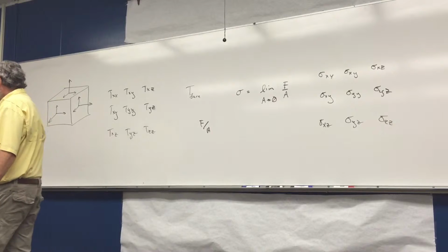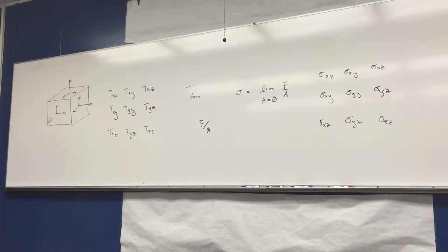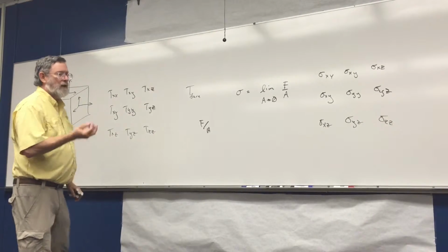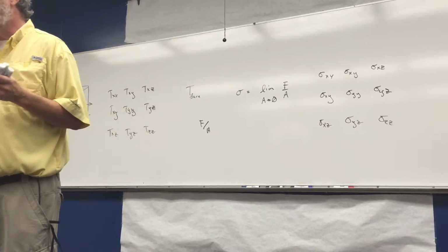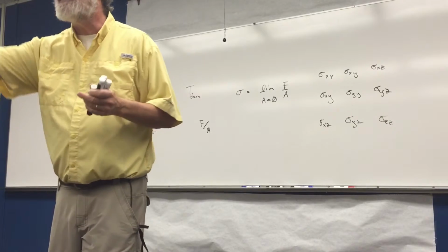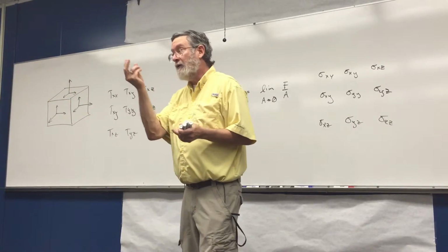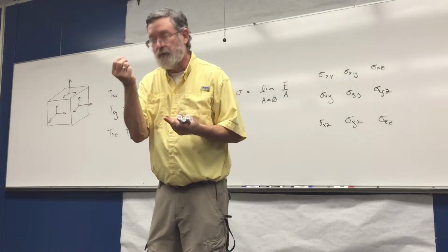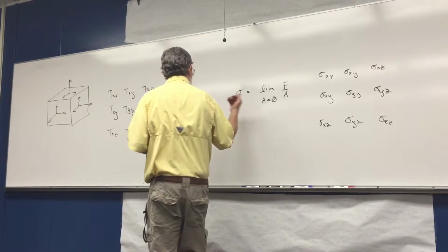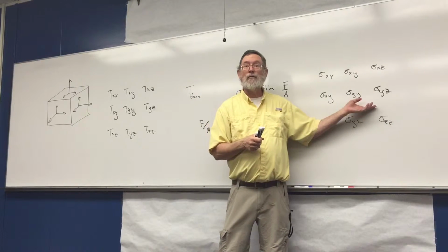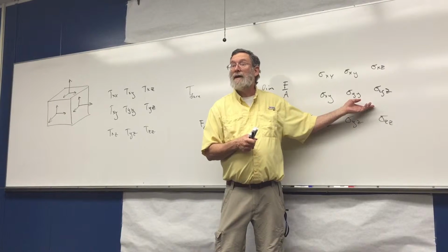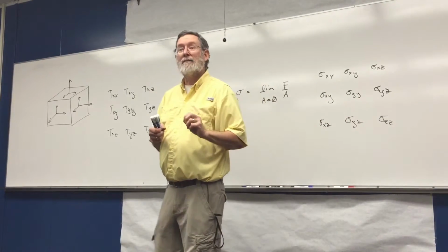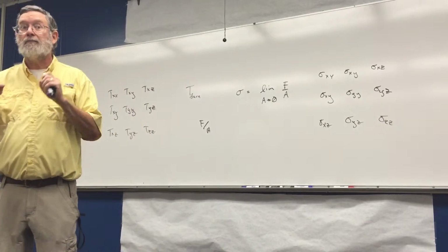We started off with just a plane, but we had to do all these different orientations to the plane. We resolved that into a Cartesian coordinate system cube, if you will, to then resolve that we can move throughout our body. And now that's cumbersome, so we shrunk the cube down using the limit, and we have our definition for stress at a point. It cannot rotate within that material body. Okay? So we're good?